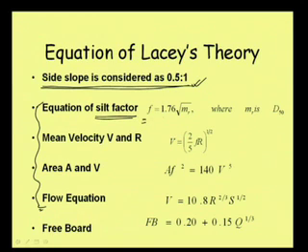Silt factor F, he gave this formula as 1.76 root over MR, where this MR basically represents the particle size, and that MR is considered as D50. So, for the application of Lacey's theory, if we go to the field, first we should collect the sample through which the channel will be made.